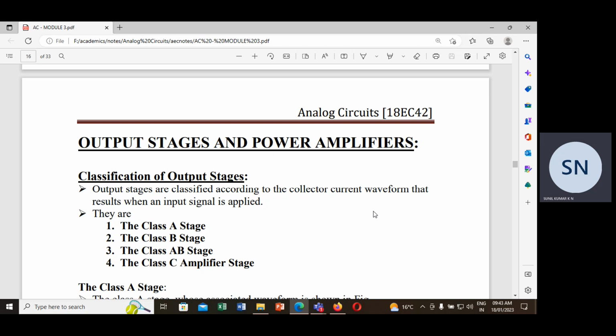The same thing, if I connect a feedback, the gain is going to reduce. The op amp gain is going to reduce if I employ negative feedback. Negative feedback is connected to the inverting input. If I connect the output back, the gain will be reduced. You will not get a gain of 10 power 6. You will get the gain as RF by R1. That is, what type of amplifier will have the gain as minus RF by R1?